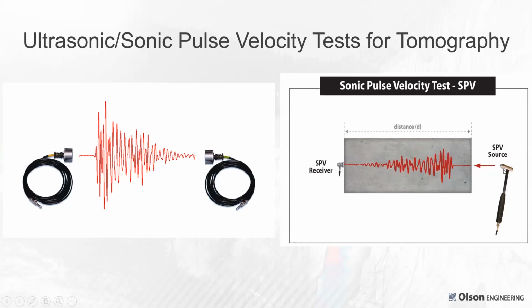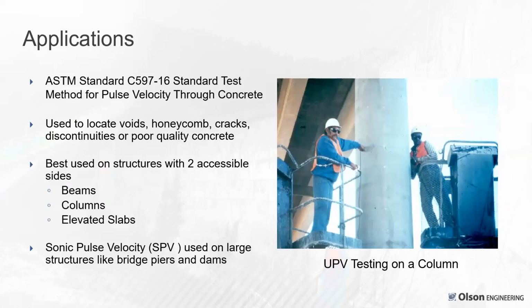Lower frequencies could be a fairly small hammer, starting off at 0.2 pounds with an instrumented load cell built in to measure the impact force and timing. And then a receiver. It could be an accelerometer. It could be one of the ultrasonic pulse velocity transducers as well. Or getting up to a 3-pound hammer. We often use a 3-pound impulse hammer with a hard plastic tip on dams, as you'll see. So there is an ASTM standard for this as well, and it's also in the ACI 228.2 document.